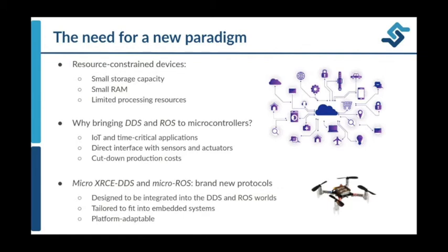And so why do we need to change the paradigm of the protocols that Jaime just exposed? This is basically due to the fact that both DDS and ROS2 are very heavy libraries, mostly programmed in languages such as C++, that are unfit for these resource-constrained devices that I was just describing, such as microcontrollers.